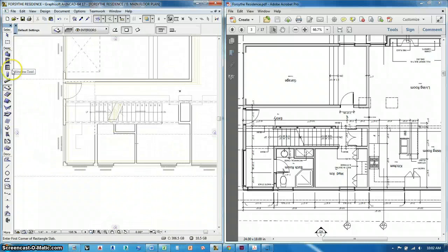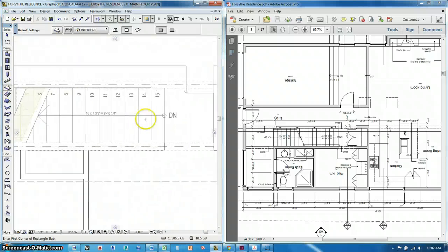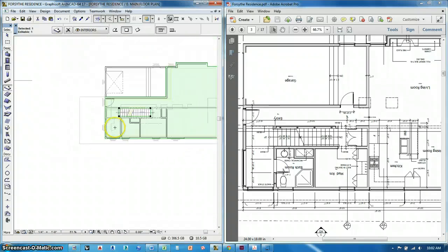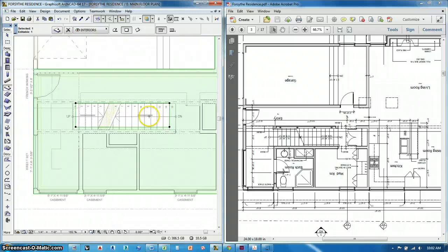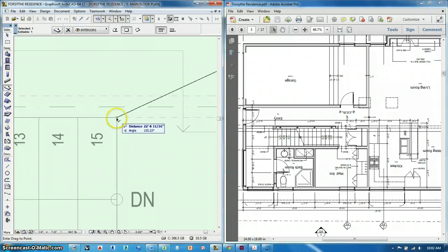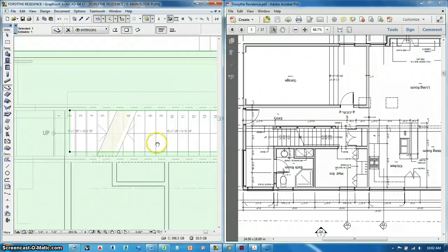If I select the slab tool and then select my slab, this line right here is what's happening with the slab. If I just select the hole itself, you can see that it only gives me nodes inside, so I can actually move the hole itself as one object. So I can do Control D, and I can move the hole around within the slab, which is kind of funky. So I'm going to move it right over here, which is where I want it.